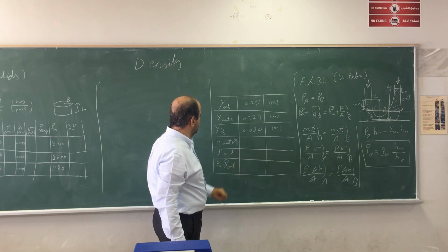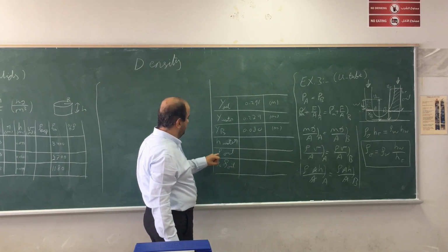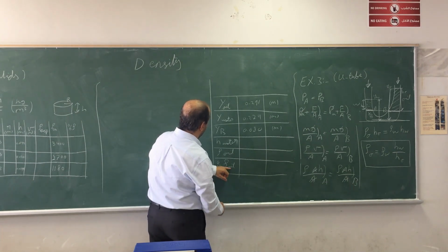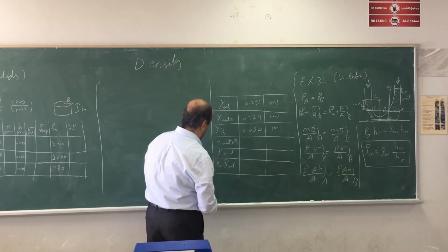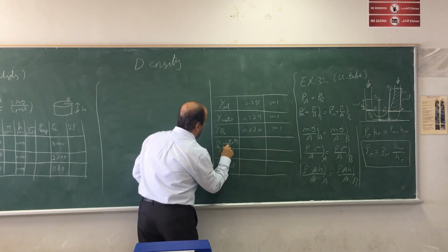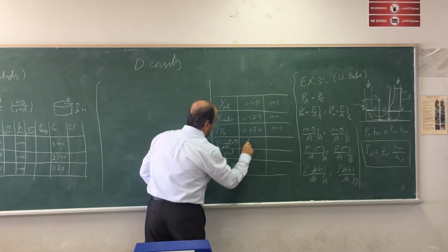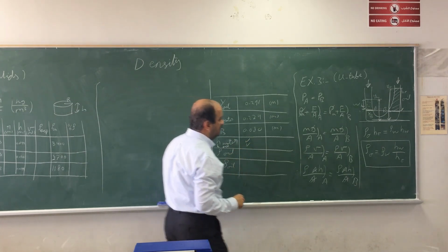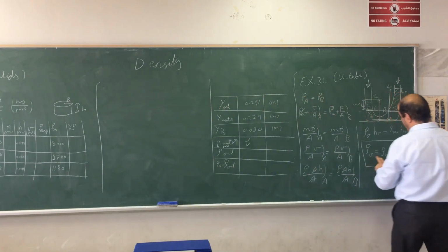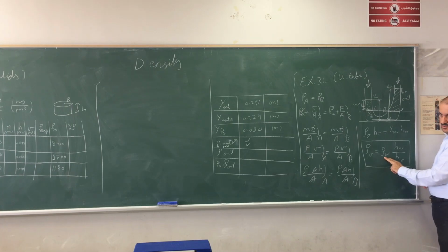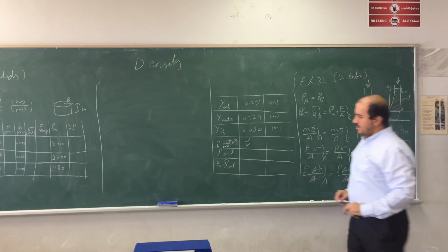Accordingly, you can measure the density of the oil, and you can measure the percent difference also in the oil. Also, you have to add here the height of the oil. You can measure this value and this value, and then you can find the density of the oil. The density of the oil equals the density of the water, take it 1,000 kilogram per cubic meter, and multiply it by HW divided by H of the oil.